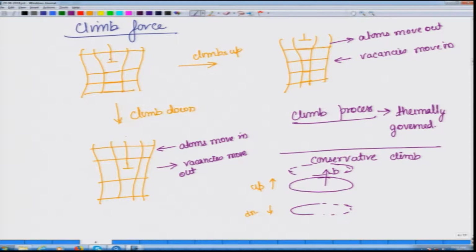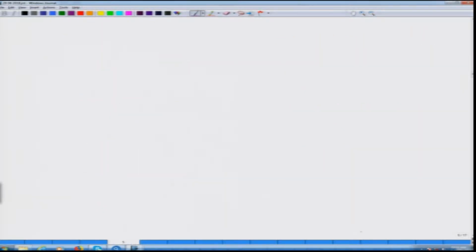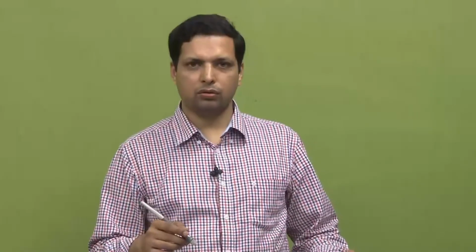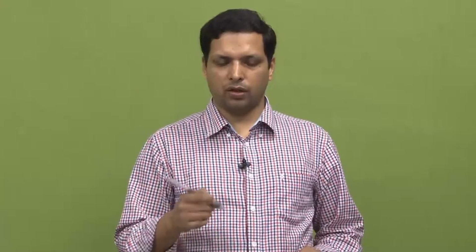Okay, so, coming to the approximate relation for this climb. Now, here what you have to first realize is that again you can have external stresses as well as internal stresses. You need thermal agitation, but stresses can also cause the dislocation to climb, basically adding additional stress for the dislocation to move, and this additional stress can be external or internal.